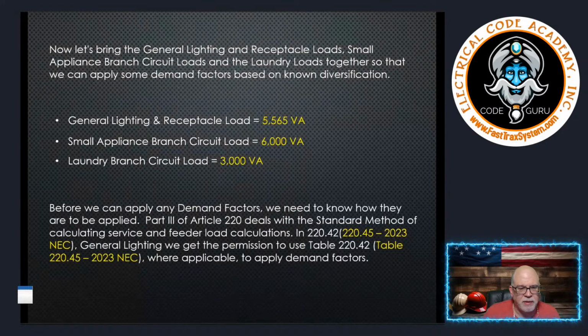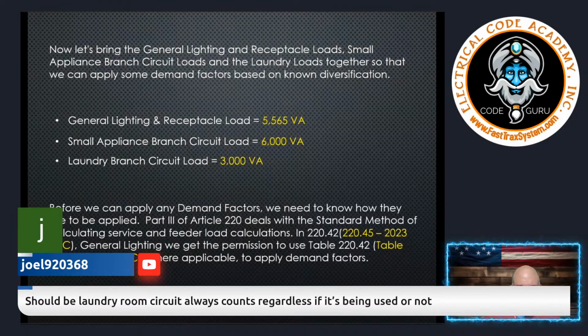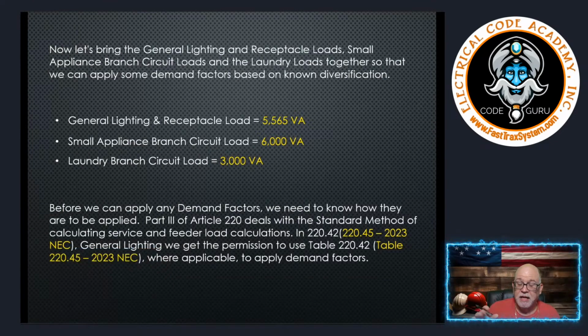Let's see here. Question we had from the chat is, should the laundry room circuit always be counted regardless if it's being used or not? You have to have a laundry circuit, period. Unless you're dealing with a multifamily dwelling that has a laundry facility on site that is available to all of the tenants or all of the renters, then it doesn't matter whether you use that laundry room or not. You have to have at least one 20 amp laundry circuit.